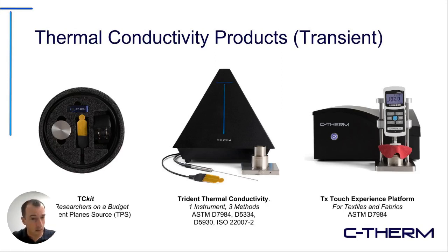That said, the third sensor is very interesting and really provides some advanced capabilities, and that's the hot disk style transient plane source sensor. The end of that nickel foil that's encapsulated in the yellowish polyimide is a disc shape, and that is sandwiched in between two samples. And this is a very complementary method to the MTPS technique, which is simple, easy to use, very accurate, but a bit more boxed in terms of the experimental parameters.